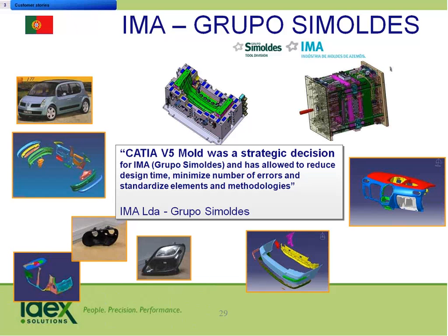We also have the ability within plastics, deformation of plastics and everything else, to control how it deforms. It's actually very, very accurate. We took one customer that was doing the stamping process by hand. They would stamp it, then test it and do the molding and everything else by a hand process. They were usually looking at about 20 to 30 tries. They're now down to 1 or 2 tries to get the tool exactly what they want. So a huge, huge reduction in time.